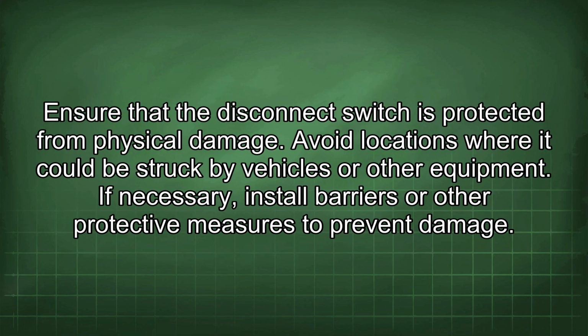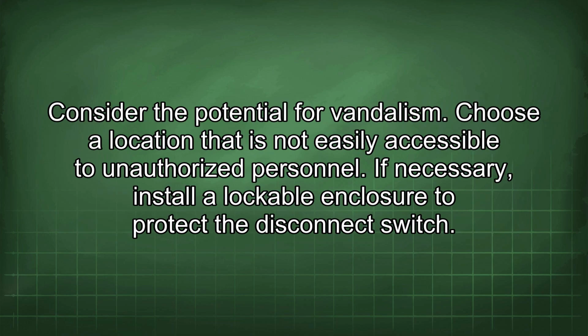Ensure that the disconnect switch is protected from physical damage. Avoid locations where it could be struck by vehicles or other equipment. If necessary, install barriers or other protective measures to prevent damage. Consider the potential for vandalism. Choose a location that is not easily accessible to unauthorized personnel. If necessary, install a lockable enclosure to protect the disconnect switch.